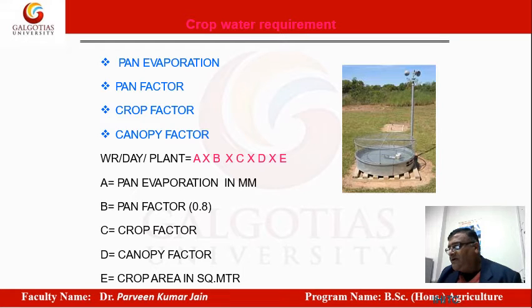And then the canopy factor is how that crop has canopy. I hope you all know that the canopy is the coverage, or the shade effect of the tree or plant on the ground, and on the basis of that, the canopy factor, the ET depends. The transpirational losses or evaporation losses are more from naked soils as compared to covered crops.